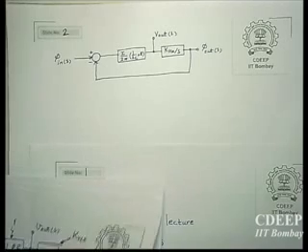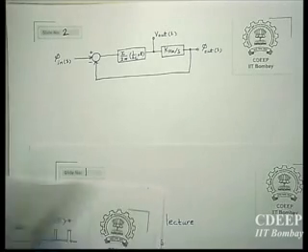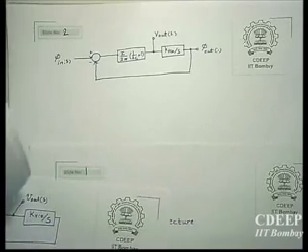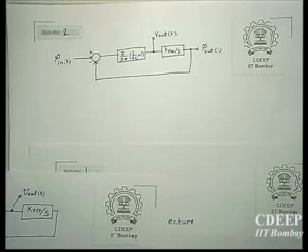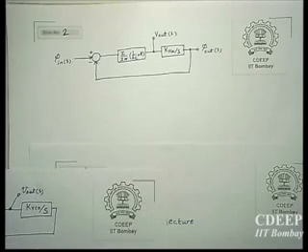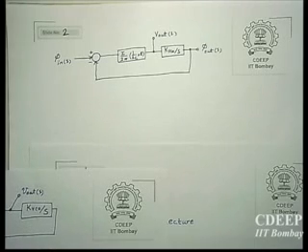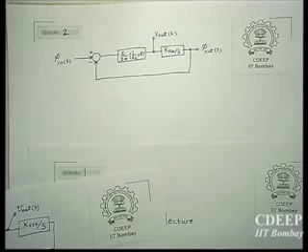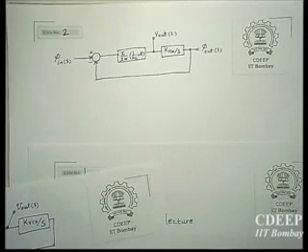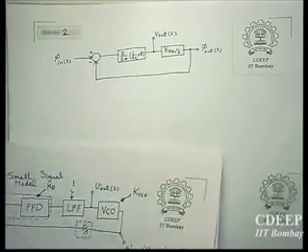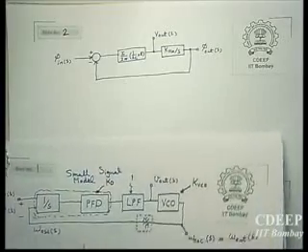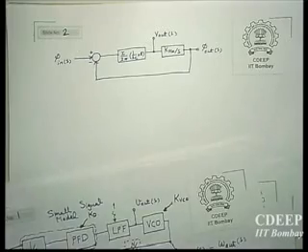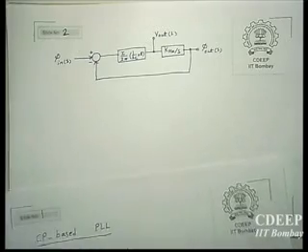So if you notice at low frequencies, actually effect of R is not considerable. Right? So therefore at low frequencies, actually your loop is the same as before. At low frequencies. So one may expect, okay, at low frequencies therefore system will be unstable.